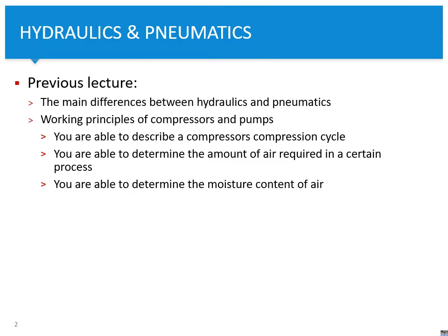So in the previous lecture we discussed the main difference between hydraulics and pneumatics. In pneumatics the fluid is compressible, and in hydraulics the fluid isn't compressible, so it's a liquid. And we discussed some working principles, mainly of compressors and pumps. From there, you learned how to describe a compressor cycle, and you learned to determine the amount of air that is required in a certain process.